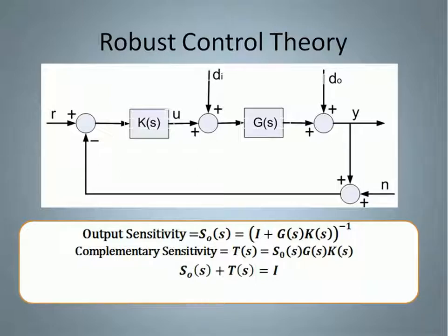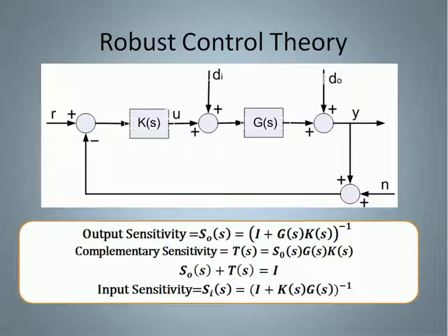If we are designing, for example, a controller to satisfy certain requirements for the output sensitivity, indirectly we are also fixing the closed-loop transfer function, and with that we are setting some performance features about the following of R, good or bad. We will talk more about this later. And finally, we have the input sensitivity given by this equation at the bottom.